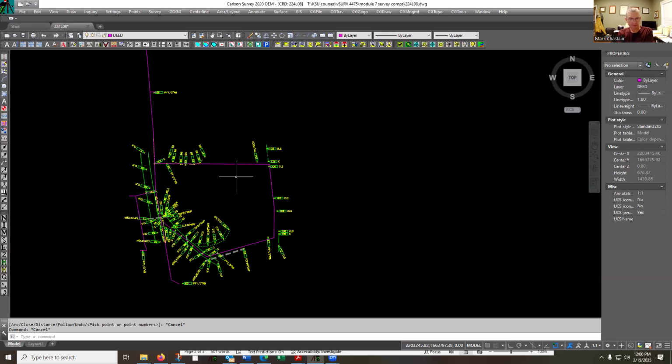If you have that available in the county that you're working from the GIS department, we get that from a couple of different sources where we pay for it. If you're on grid, especially if you'll just do the slight tinkering to scale it, then you're good. And it'll drop right in. You can just turn all that on and everything fits, which can be important, especially if you're trying to figure out when a road or some sort of encroachment or improvement on the property came to be.